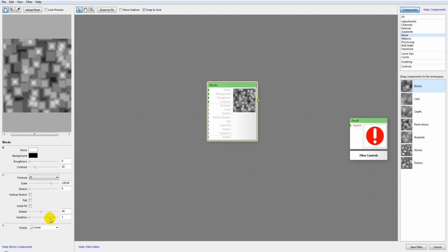Okay, next we also have the option of details. That is a control input, and details will adjust the complexity of our image. Sometimes we may need to increase some roughness or other details so we can see some complexity on this. One thing: large details values will also lead to longer render time, so just beware. When you increase more details for your noise, it will increase the time that needs to be calculated by the formulas.